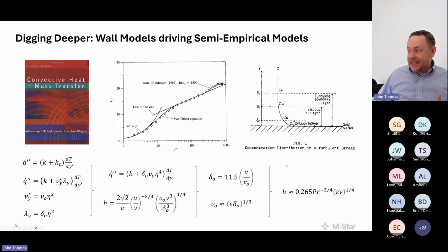These are really cool. This is kind of a cool idea. Now, why have we not littered the world with these correlations? Why is this not the first thing you learn when doing convective heat transfer modeling? Well, it's because energy dissipation is, generally speaking, a hard thing to calculate. Unless we have a well-defined system, we may not know the energy dissipation at the wall, right?